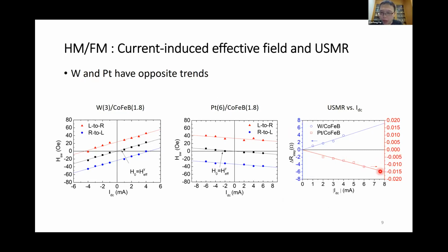So even if you apply the DC current up to say 6 milliamp, the delta R that you'll see is maybe only 0.01 ohms. So it's actually very small, at least for the DC type of measurement. I think if you use AC, maybe it's larger, but for platinum base, typically we probably need to use AC, use lock-in to see a much cleaner signal.